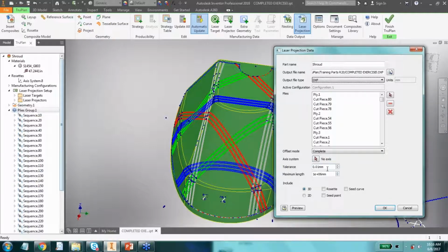These are all throwbacks from the legacy system. We did do a slight change to the resolution, angle, and step commands that we had in the legacy product. They have been replaced by tolerance and maximum length, which end up having the same effect. So the tolerance controls points along any curved surface, and the curved boundary that actually curves and is not a straight line. The maximum length would take more effect on those straight segments and force additional points where we need them.